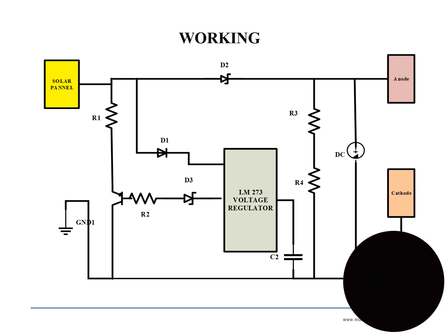The proposed and built circuit for providing impressed current over the iron pipe using the impressed current cathodic protection approach is as shown. The solar panel output voltage is delivered into the LM723 regulator as an input. Voltage regulation and prevention of battery overcharging are two functions of the LM723 regulator. The iron pipe and graphite serve as the cathode and anode with DC supply.